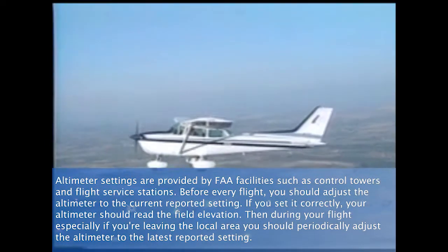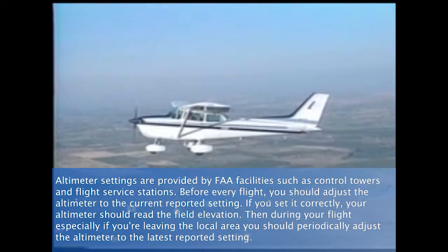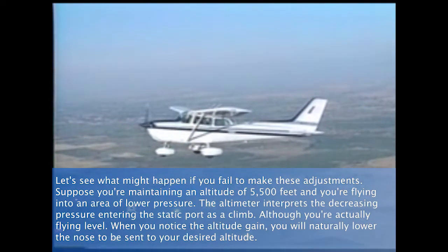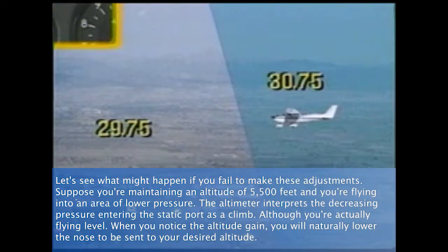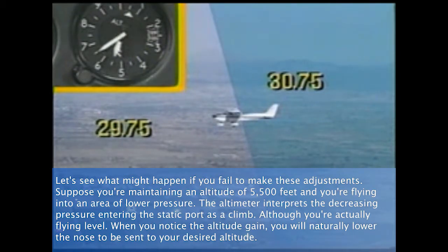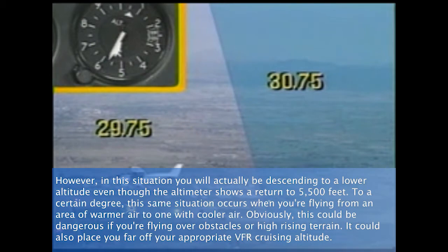Then during your flight, especially if you're leaving the local area, you should periodically adjust the altimeter to the latest reported setting. Let's see what might happen if you fail to make these adjustments. Suppose you're maintaining an altitude of 5,500 feet and you're flying into an area of lower pressure. The altimeter interprets the decreasing pressure entering the static port as a climb, although you're actually flying level. When you notice the altitude gain, you will naturally lower the nose to descend to your desired altitude. However, in this situation, you will actually be descending to a lower altitude, even though the altimeter shows a return to 5,500 feet.